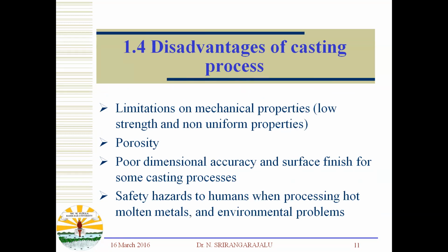Next, disadvantages of the casting process. Limitation on mechanical properties, low strength and non-uniform properties, porosity, poor dimensional accuracy, and poor surface finish for some casting processes. Safety hazards to humans when processing hot molten metals, and environmental problems.